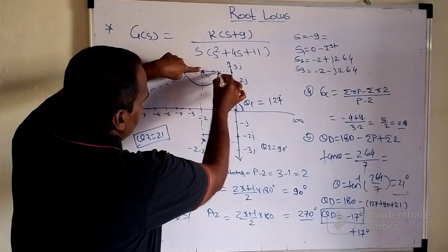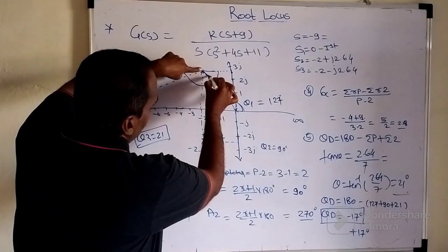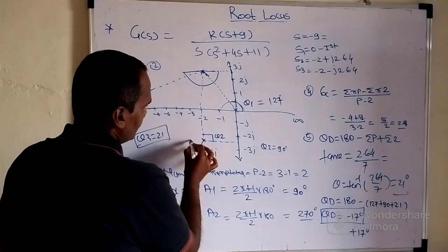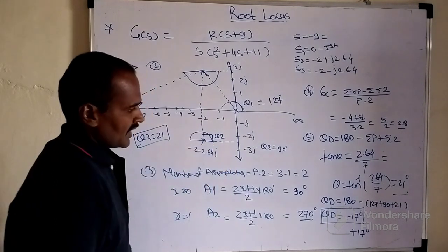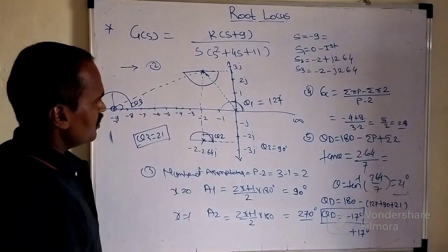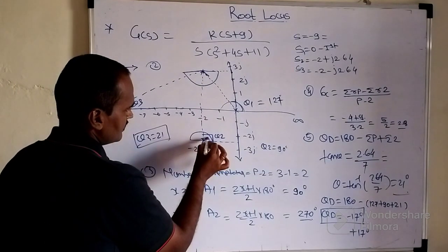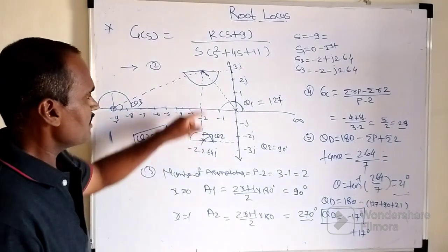Minus 17 degrees. So from here 0, 10, 20, somewhere here we will have this 17 degrees, right? And similarly for this pole we need to put this protractor like this, right? And the angle of departure is how much? It is plus 17 degrees. So like this, somewhere we have this plus 17 and minus 17.